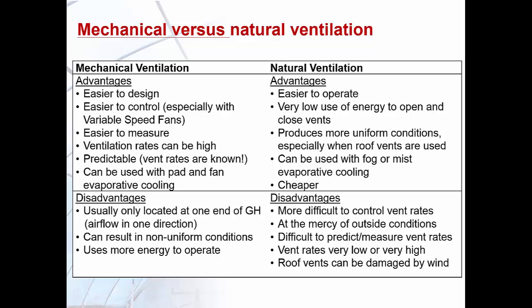Natural ventilation systems, meanwhile, are easier to operate, and they use very little energy to open and close the vents. More uniform conditions in the greenhouse can be achieved. This system can be used with fog or misting systems using evaporative cooling, and natural ventilation is cheaper.